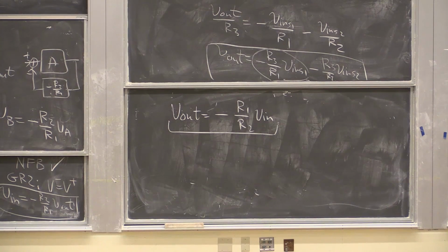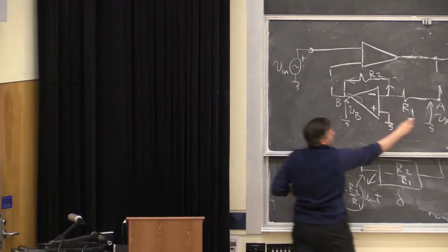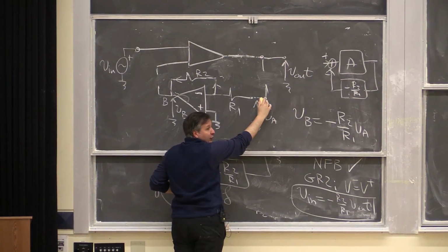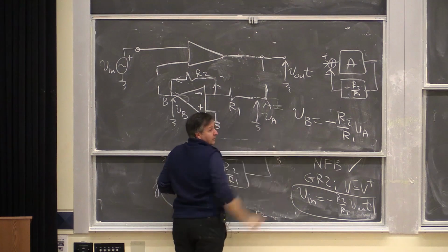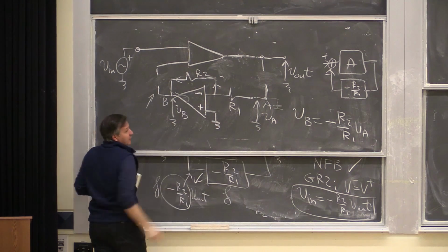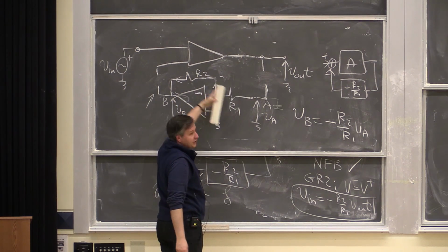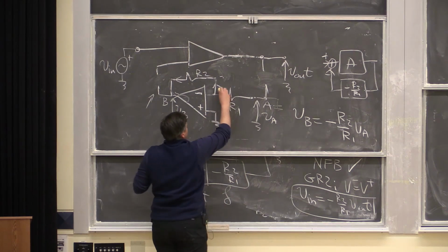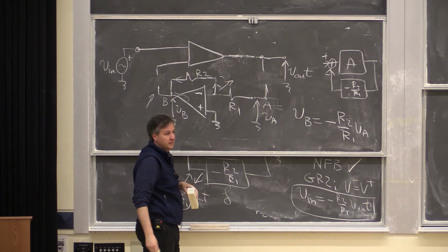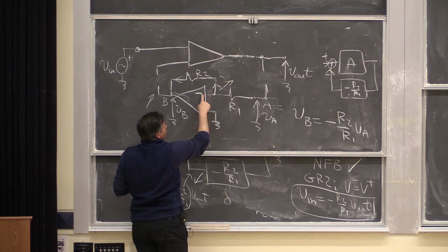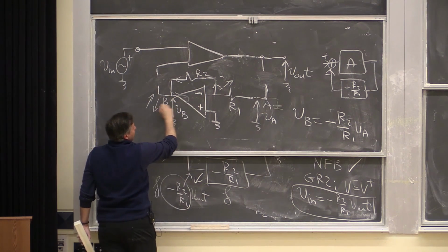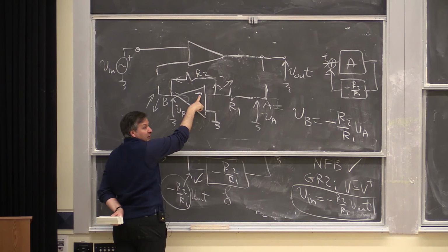So, at the very beginning we looked at this circuit. This is exactly the inverting amplifier that we did at the beginning of the lecture, so I could do it again. You assume that this is the input, so the input is nulled. If you increase the output, there's no current flowing here, so this is just a voltage divider of R1, R2. So this voltage has to increase as well. If this voltage increases and you want the output to decrease, then you have to be on the negative terminal.